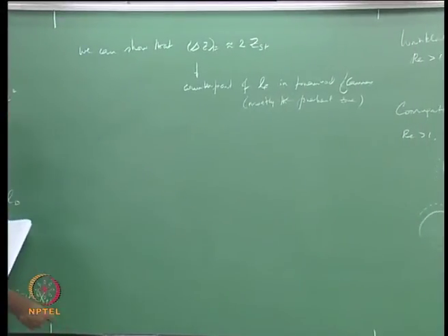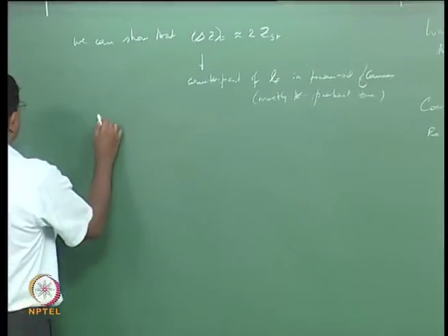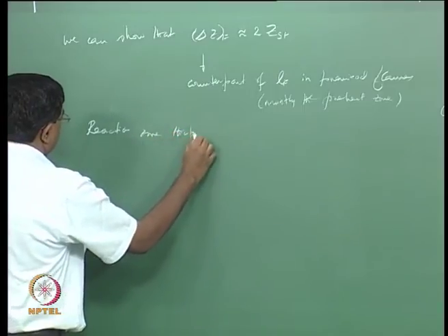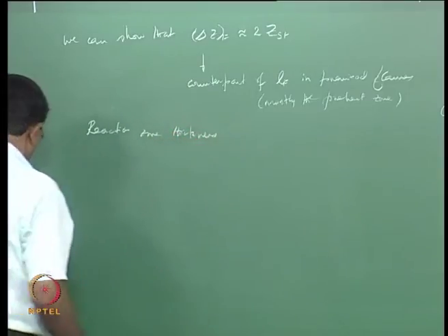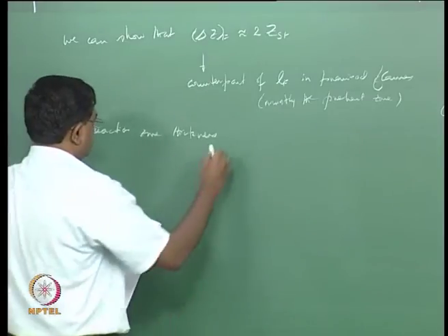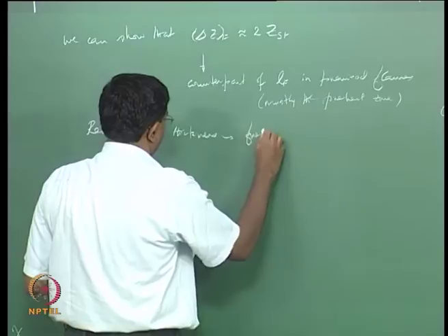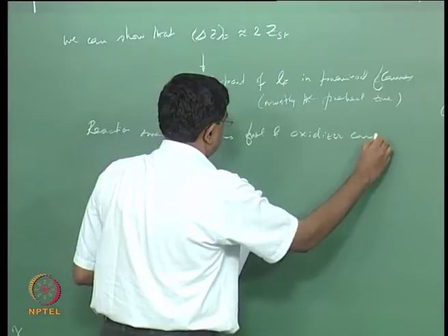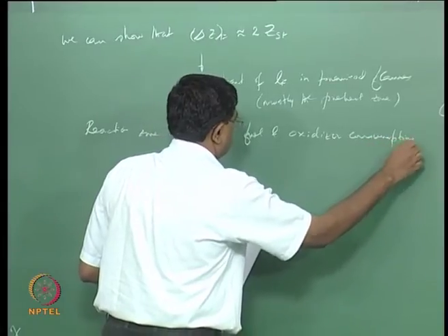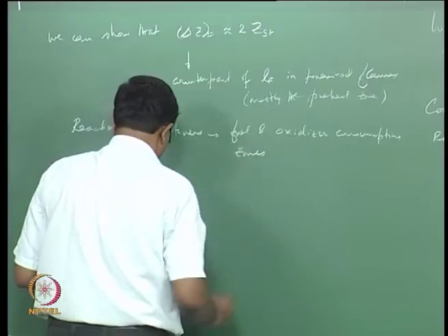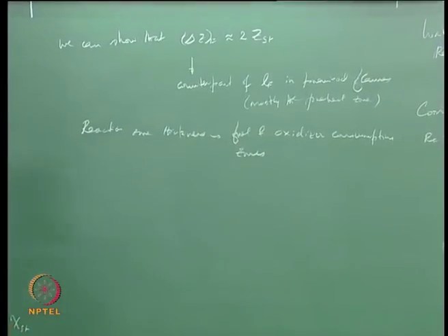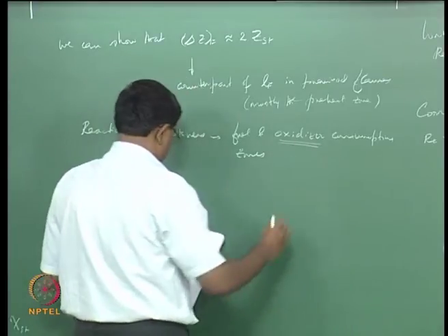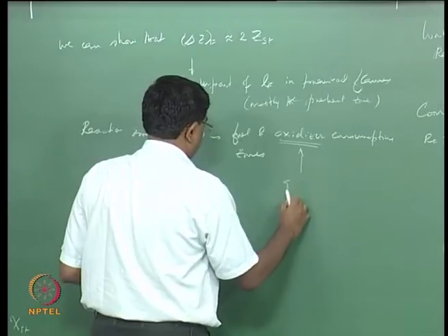Now the reaction zone thickness, on the other hand, is the one where you have the fuel and oxidizer consumption zones, and we would like to point out that the oxidizer consumption zone is actually quite larger in reality.